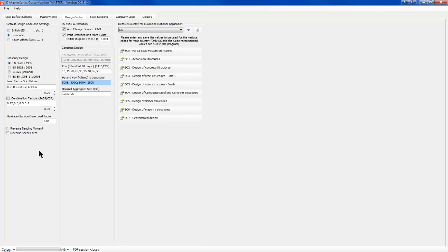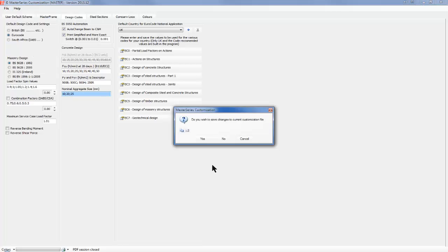Now, it is recommended that you don't use H. H is the general 500 grade, and H says use A, B, or C of the steel grades. But the problem there is that if you use 500A, 500A is not great at yielding. So if you're doing any plastic redistribution or anything like that, it's not recommended. Its elongation is very, very poor. And then we have our nominal grade. So I'm just going to come out here, saving this with that modification, exit using current settings.